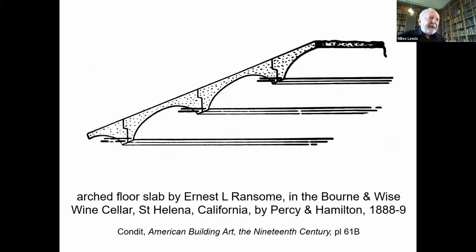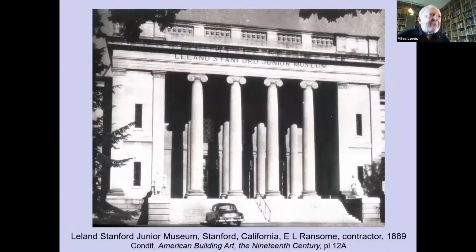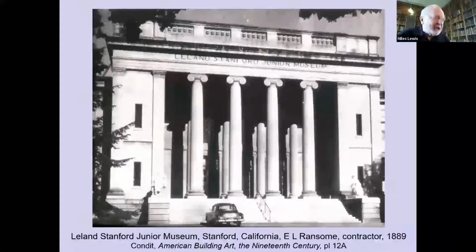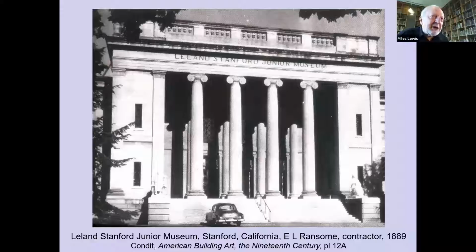Then in America, this is really quite an effective design here. These units, because they curve down, get some depth, where the rods are placed for taking the tension, and the thick part of the arch is taking the compression, so it's quite a scientifically disposed system. These are all precast units, and essentially the same thing was being made quite commonly in, for example, Melbourne into perhaps the 1960s as a regular flooring system. That building, though, once again on the outside, doesn't look very strikingly modern, although the structure was so advanced.